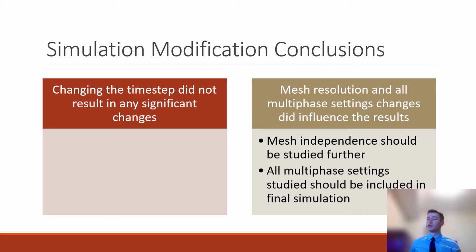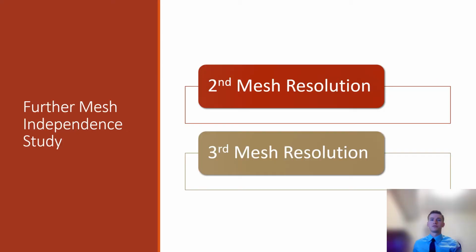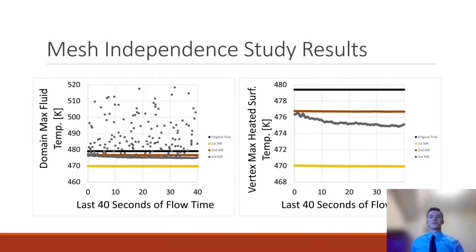However, the mesh resolution and all multi-phase settings changes did influence the results significantly, so mesh independence should be studied further, and all multi-phase settings should be included in the final simulation. To further study mesh independence, two more models were run, this time with a second increase in mesh resolution and a third increase in mesh resolution.